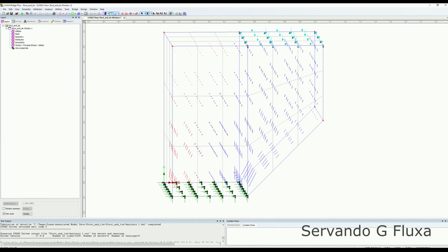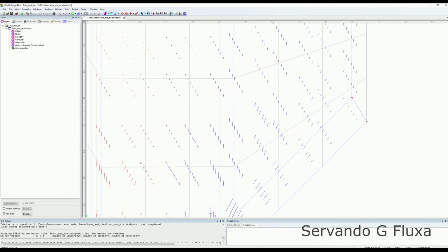So your reinforcement should go all the way up here. Theoretically, you won't need reinforcement here because the tensions are minimum, but of course you cannot go from here to there while defining reinforcement in a concrete section. So we'll go from here to there, and then you also need reinforcement here.